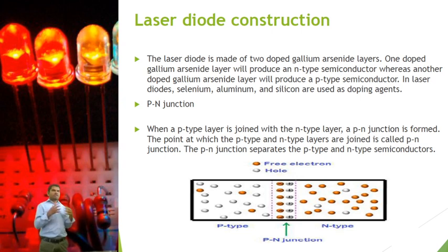When we connect the P-type and N-type, the electrons move in one direction and the holes move in the other direction, and this movement generates an electrical signal. The P-type of the semiconductor device is connected to the positive terminal of the battery, and the N-type to the negative terminal of the battery.